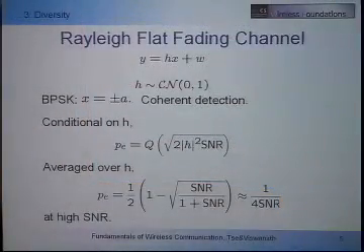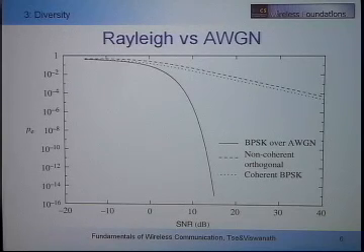All right. So now we plot the performance. Wireless engineers love to plot things. So we plot a lot of stuff. As a function of the signal-to-noise ratio in dB scale, I'm plotting my error probability, also in log scale. So here is my AWGN channel, the solid curve at the bottom. You can see that if I increase my SNR, the error probability falls like crazy, and that's an exponential decrease. This is the so-called waterfall curve. Water is falling. All right?